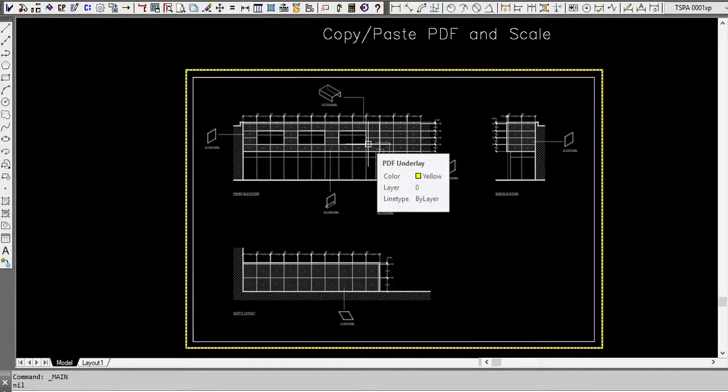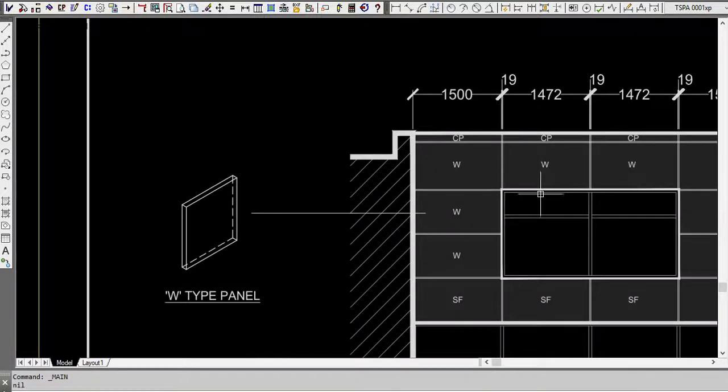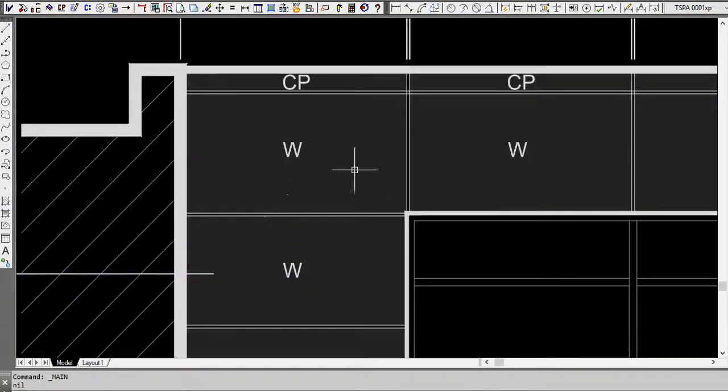So if you have a high quality PDF, you can come in here and usually just take a shape like this and click using the boundary panel utility, and it would put a panel in each of the clicks. However, you can see how thick the polylines are here, so it's not finding exactly what we're looking for, and it doesn't recognize it.